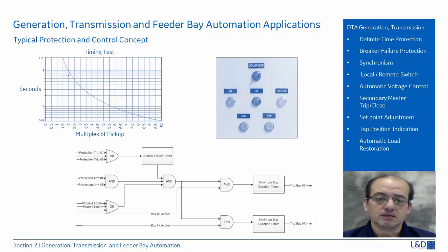Synchronism, that's basically synchronizing the voltage between two buses. And local remote switch setup. Normally we have a manual local remote switch, but you can also implement a software local remote switch, automatic voltage control, secondary master trip close, set point adjustment, tap position indication, and automatic load restoration.